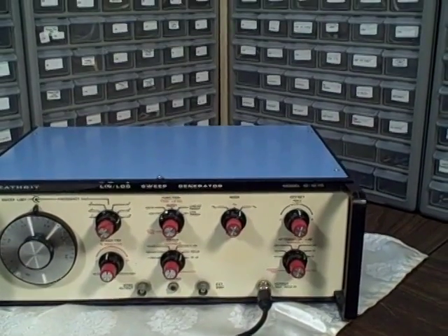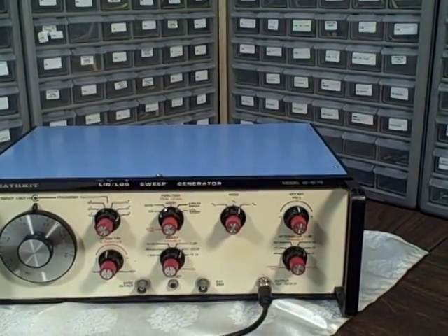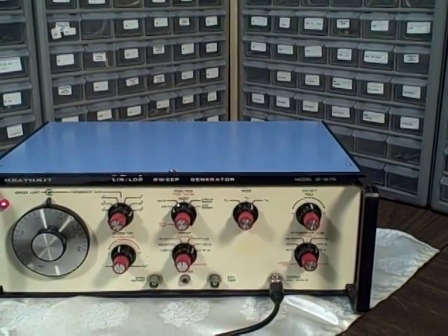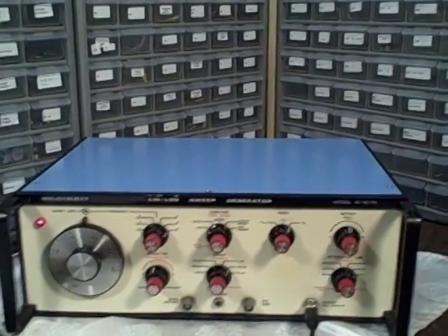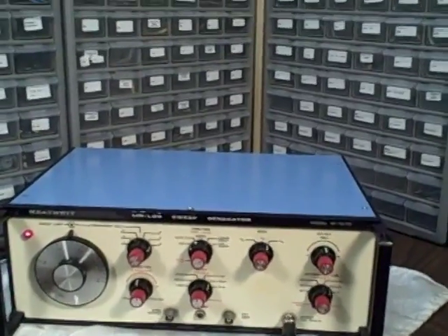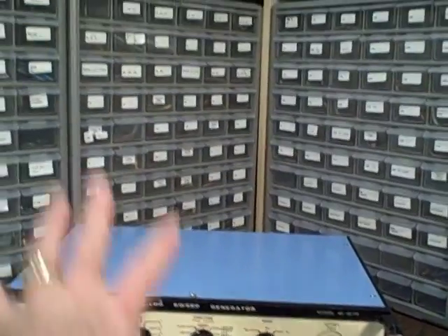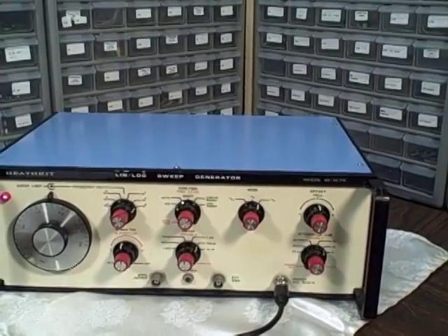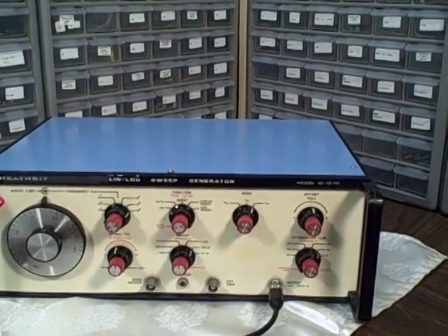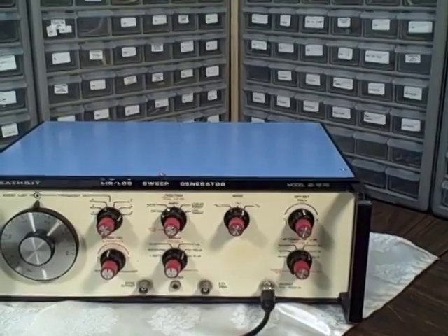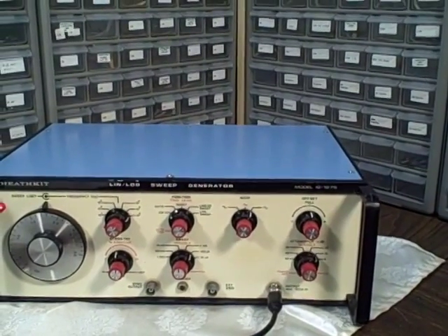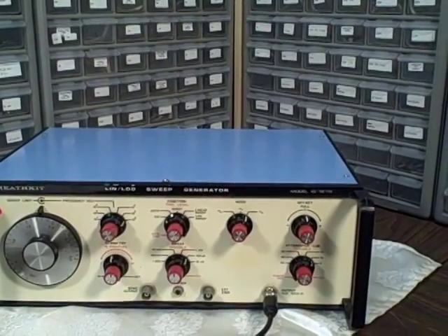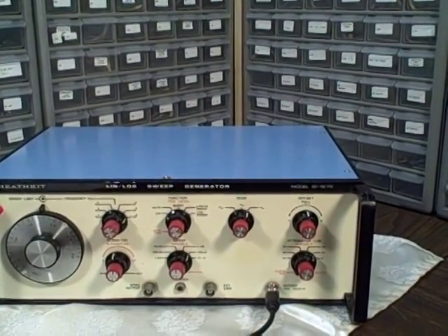This is a square wave generator, a triangle wave, a sine wave generator. It'll provide it continuously. It'll provide it gated, where we'll demonstrate that in a little while, but you can, upon demand, push a button and throw through pulses. You can get bursts of pulses, and you can control the number of cycles in each burst. And then the linear and log sweep. You can sweep at a linear rate, or you can sweep at a logarithmic rate.